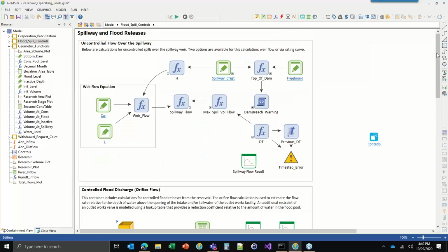But then on the upper zone, the zone above the flood zone, this is the spillway or uncontrolled flow zone, where water would just flow freely over the top of the spillway and perhaps be more of a risk downstream. So you don't want it to be in this zone. But if it ever gets there, then you would have a mechanism to get it over. And in this case, we're using hydraulics again to calculate it using a broad crested weir flow.